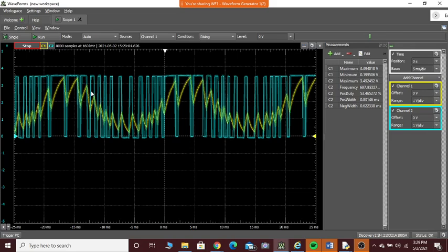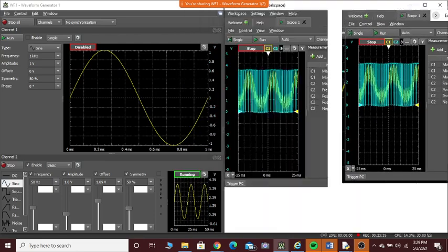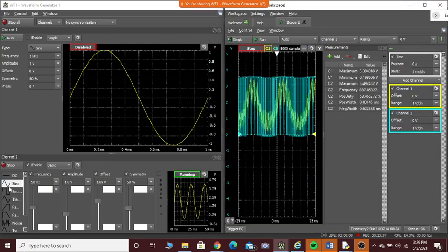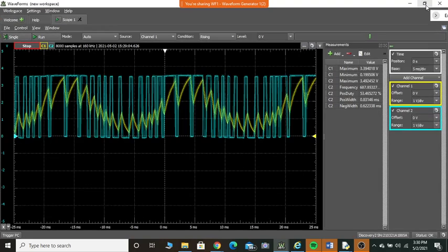This is possible by applying an appropriate sine wave of lesser frequency at the control voltage using the second channel. We are applying a sine wave of low frequency with appropriate offset and amplitude voltage, and you can get a PWM waveform. Correct?